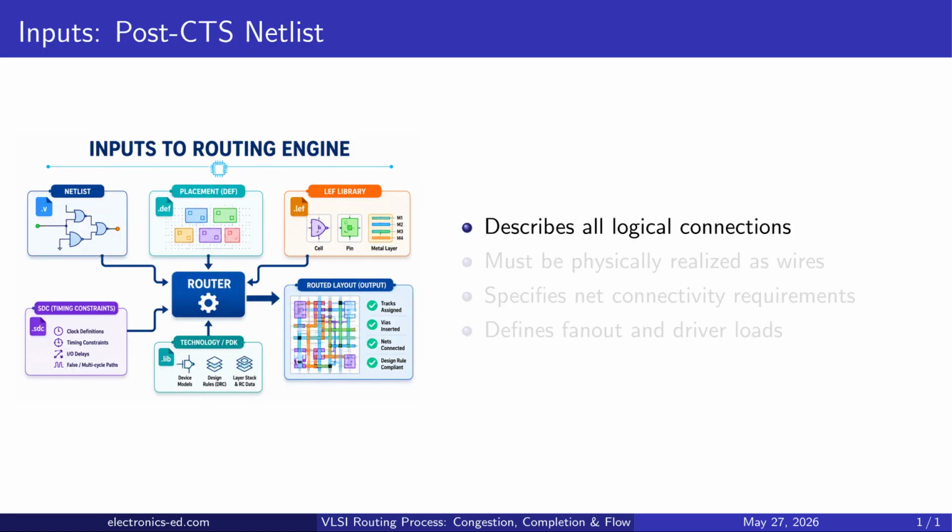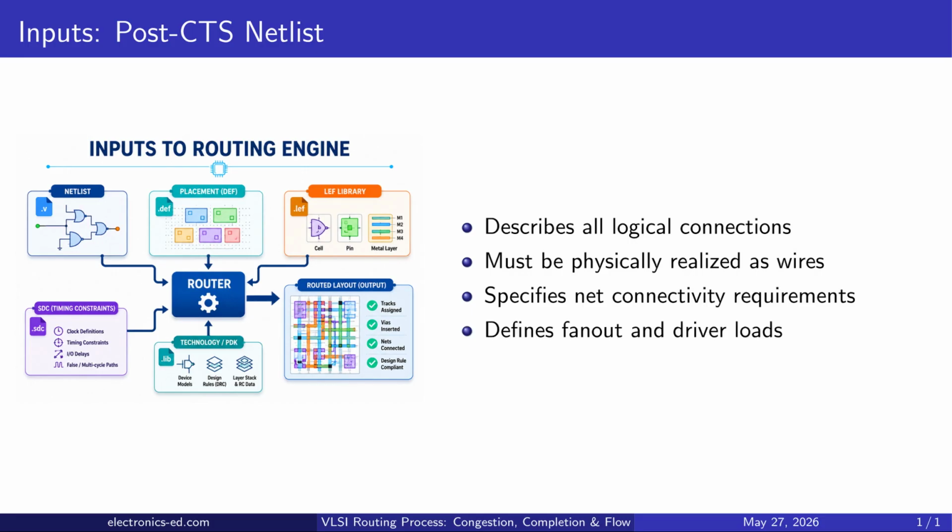The Post-CTS netlist describes all the logical connections that need to be made. Those connections must be physically realized as metal wires. The netlist specifies exactly which pins need to be connected together. It also defines fan-out and the load that each driver must handle.